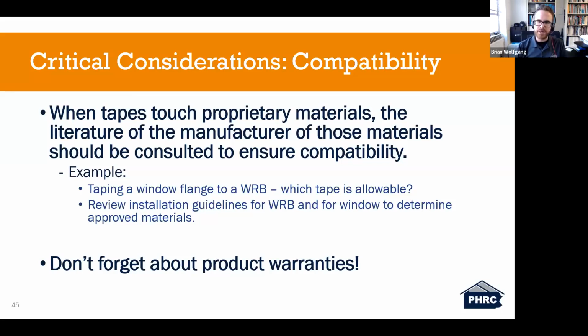But going back to that discussion of the risk that you encounter in the building enclosure, if you swap out a material for an alternative tape, is that tape of a different formulation that's going to have some sort of compatibility issue? So there is that, the core makeup of the tape. Is there going to be a compatibility in terms of, is it going to degrade? But I'm also talking about, is the tape tested and approved to be used on that substrate? And that gets more into product warranties.